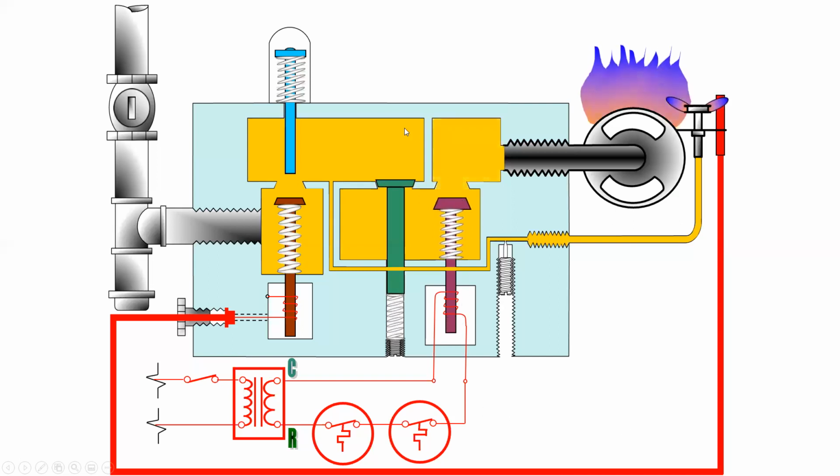When it does this, gas flows out from the main chamber to the main burner assembly, which is allowing then combustion gas to go up into the heat exchanger, and it is lit automatically simply by a flame that is always standing off to the side. When we finally do reach the temperature that the room is required to attain, the thermostat will open. And when it does, it de-energizes the main gas valve. The main gas valve closes, the gas stops flowing through to the main burner, and the flame extinguishes. Notice that the pilot flame continues to burn consistently throughout this operation.